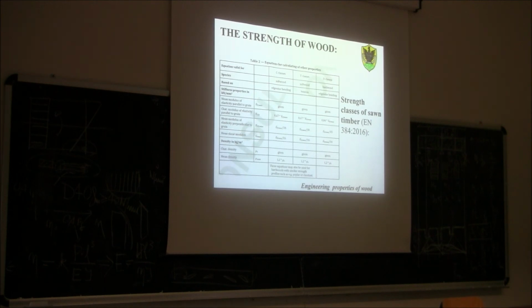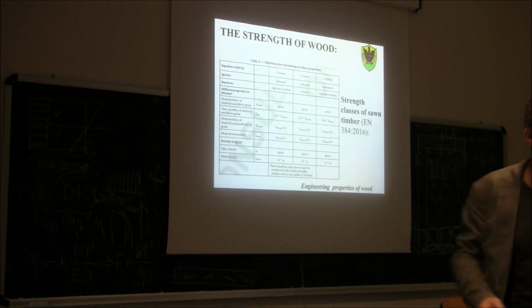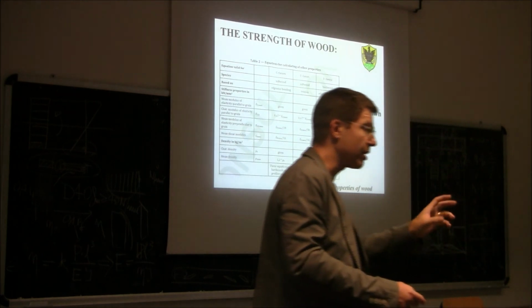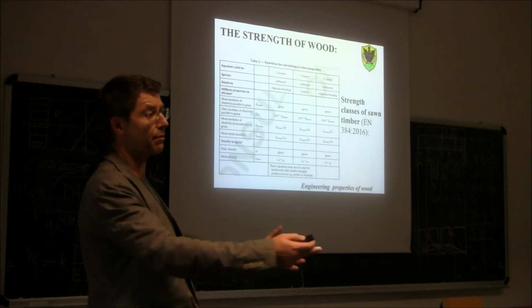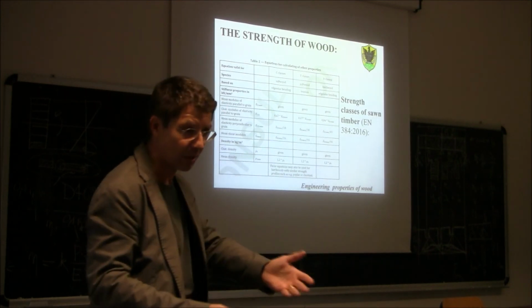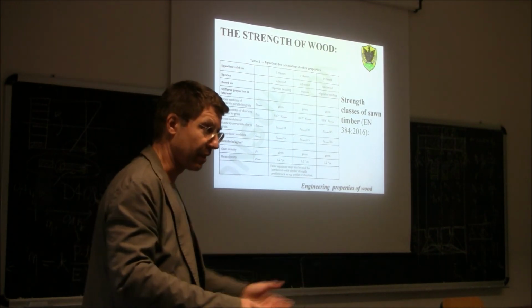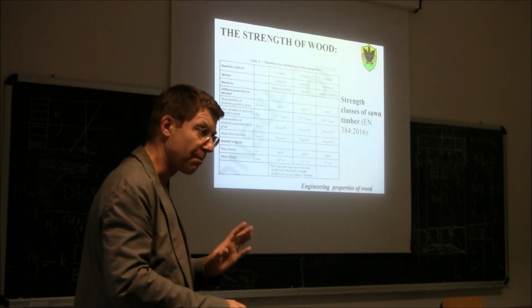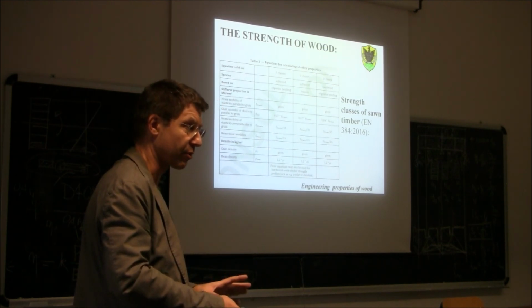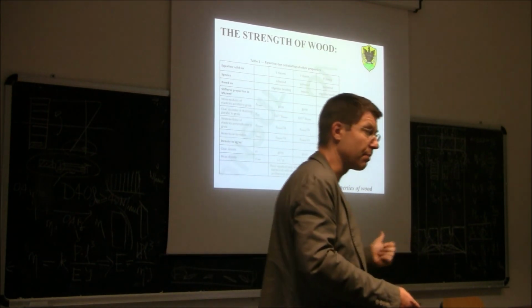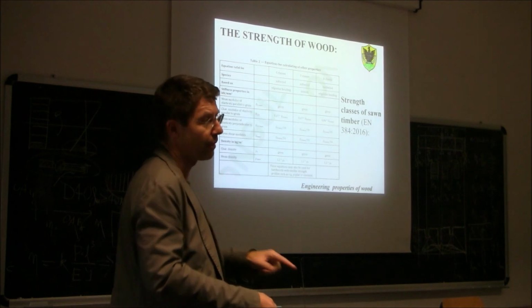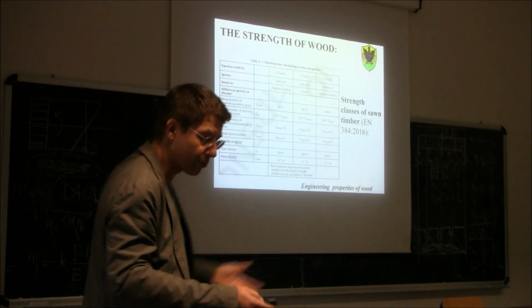For timber, it's a little bit different. In that case, G was 1/3 of E. Here it is 5 times lower. So perhaps for timber, we should think that this shear component of the deflection may not be negligible, like it is for all the other materials, like what you have done with the colleague, Professor Longo, in mechanics of structures. In fact, you will see that in this case we will have to consider it for timber, because G is much lower compared to the case of the normal isotropic material.